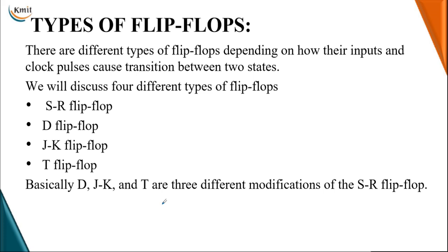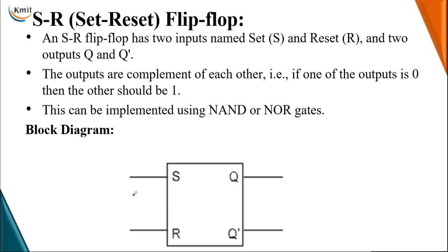So first let me learn about the basic flip-flop, which is SR. Here S means set input, and R is defined as the reset input. Why we name this a set input: if you enable the set input to logic 1, your flip-flop is loaded with logic 1 state. If the reset input is 1 and set input is 0, the flip-flop is loaded with logical 0. Hence, set input 1 sets your flip-flop or loads a logic 1.